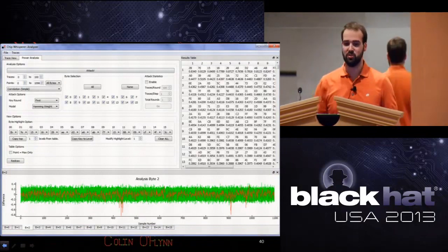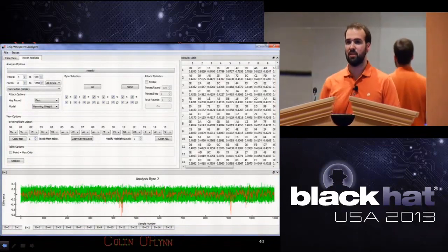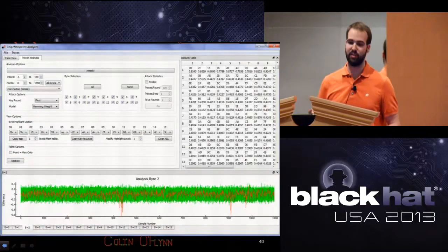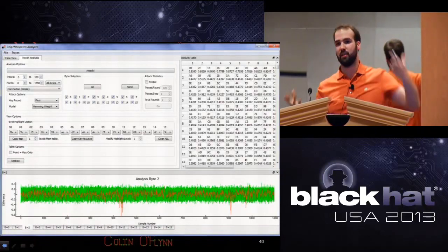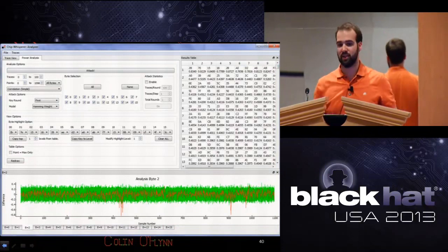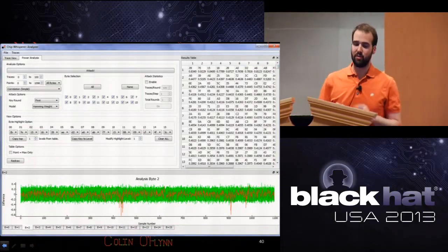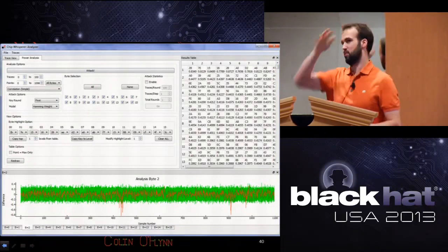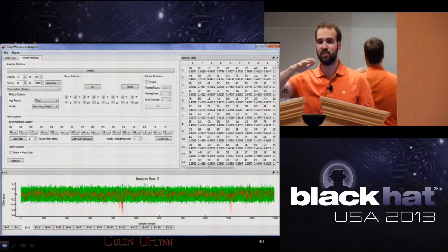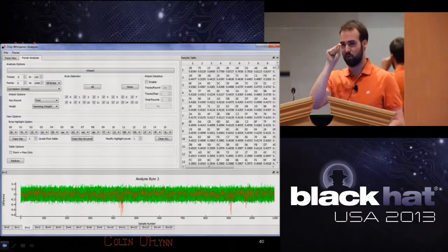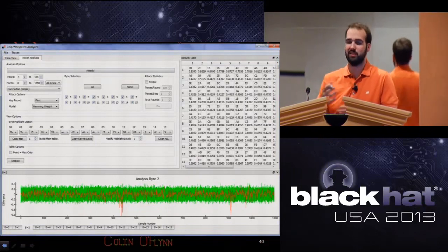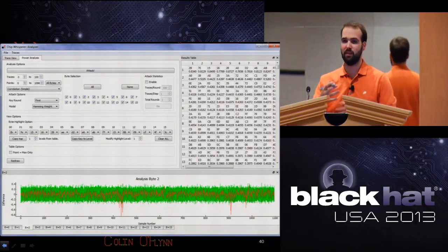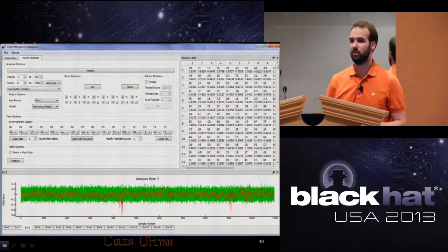But if they don't, you can also do some trace resynchronization, because in real systems you'll have interrupts and stuff that are screwing you up. Very briefly, you do some sort of autocorrelation. You correlate one power trace with the next one. You can just say, at this point, the rest of it is lining up. The convenient thing is that there are only very small variations. For example, the encryption will do a bunch of subroutine calls that are all the same, and then a bunch of stuff that's all the same. At some point, the data differs, so the power is a tiny bit different. So you will still get really good correlation between the two traces because they're mostly the same, save for some point, and then they line up as usual.